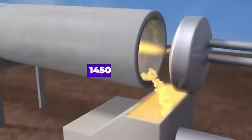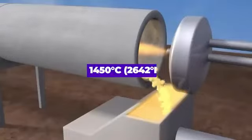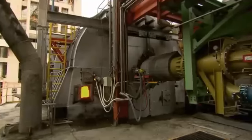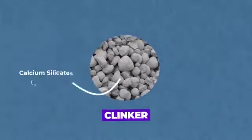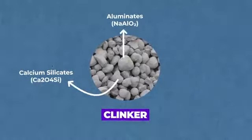The temperature in the kiln reaches around 1450 degrees Celsius or 2642 degrees Fahrenheit. In the kiln, the raw materials undergo a series of complex chemical reactions and sintering, resulting in the formation of small, marble-sized nodules called clinker. The clinker consists of calcium silicates, aluminates, and ferrites.